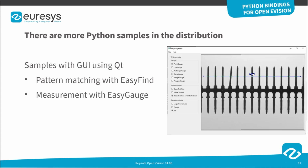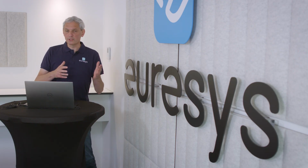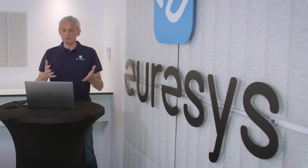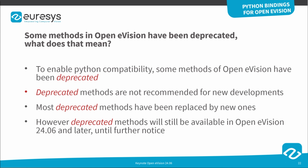And an important point is that we had to deprecate some features of eVision, some methods and classes, because the Python compatibility does not allow everything we can do in C++ and C#. So some methods have been deprecated. But what does it mean? It means that deprecated methods are not recommended anymore for new development. Of course, deprecated methods will stay available in eVision 24.6 and later. So your old application, your current application that uses these functions will compile and run without any problem. And most deprecated methods are being replaced by new ones.